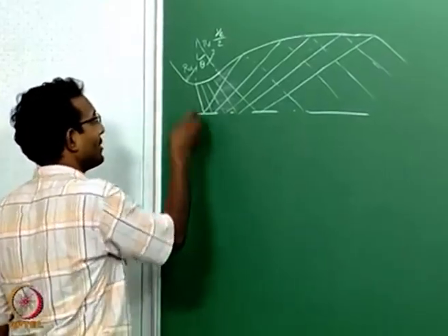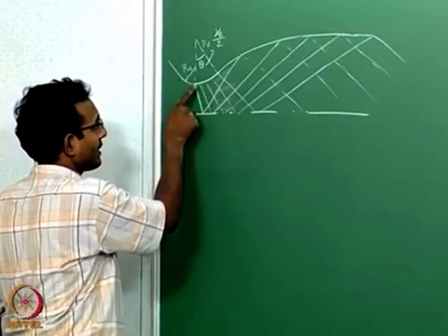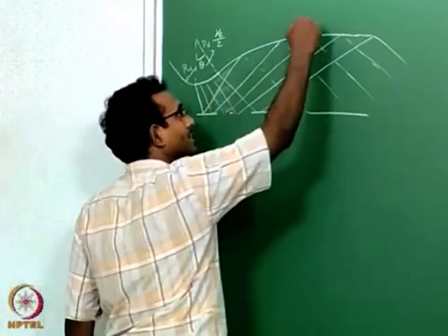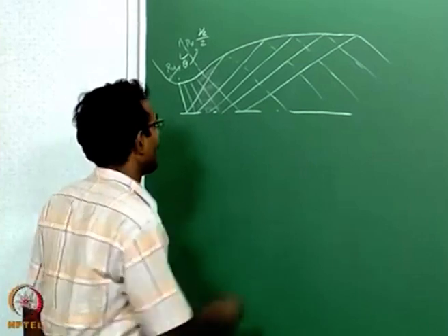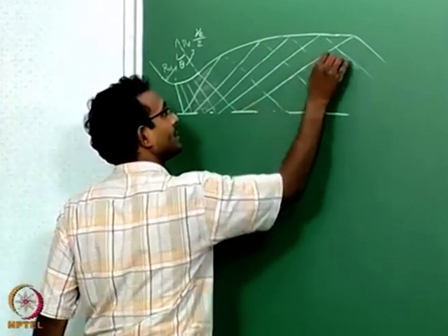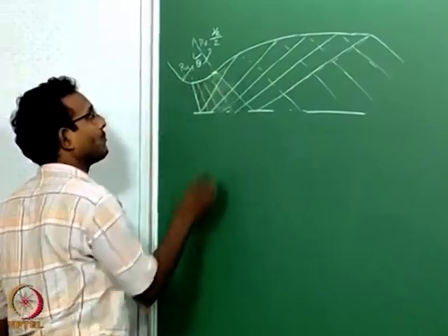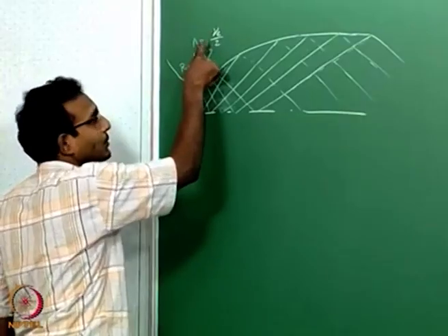Okay. What I want you to think about is from the initial point, because of this curve, it is going to be expanding. The characteristics are going to diverge as they go out, and after it hits that wall and comes back, they will all become roughly parallel. Ideally they will be parallel only after the last characteristic, which is your characteristic coming from this corner point, that point of inflection. Okay, that is the point where this theta equal to nu exit by 2 exactly.